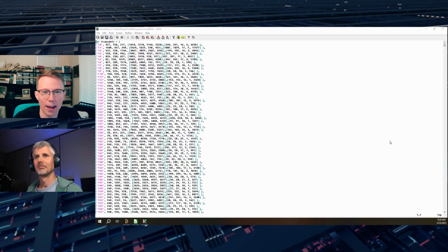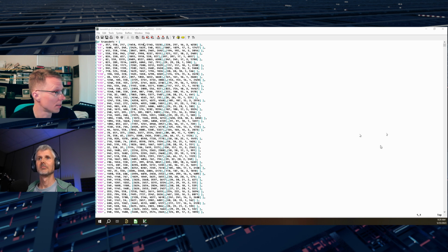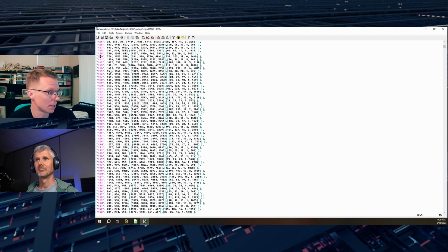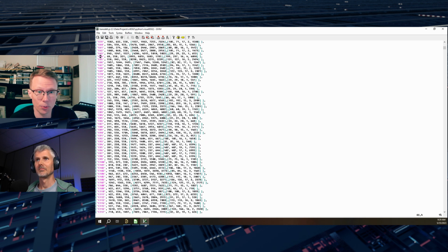And so this is what I have up on the screen here. It's just some JavaScript, and it literally has a list of transistors along with the nodes that they're connected to. So it's not a schematic, it's kind of this intermediate file here. You can see that there's this list of transistors, and then most of these numbers here, the first three are the net connections for the gate and the source and the drain. Actually, technically, they're both channel connections because they have all common substrate.